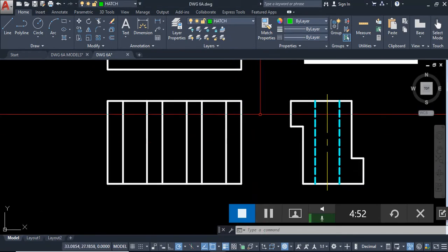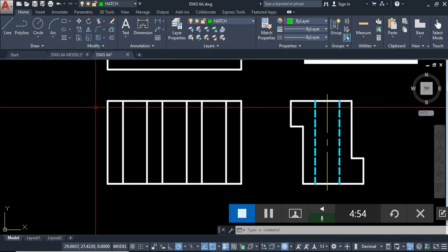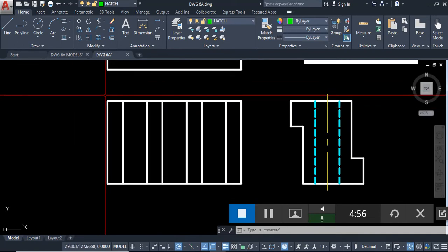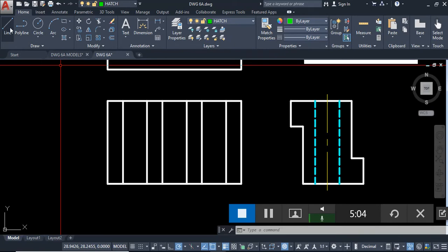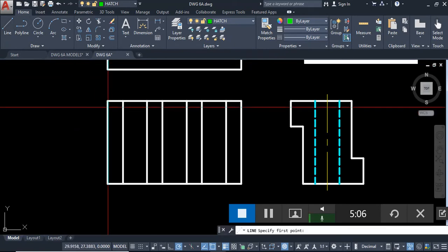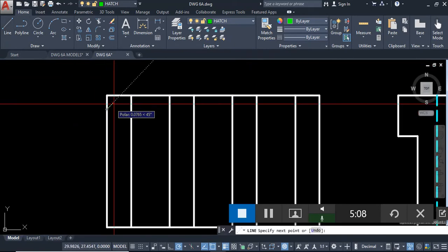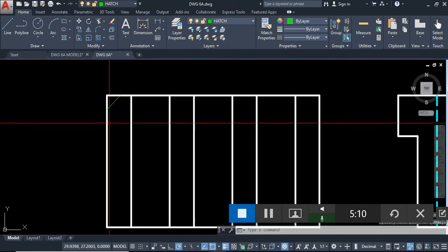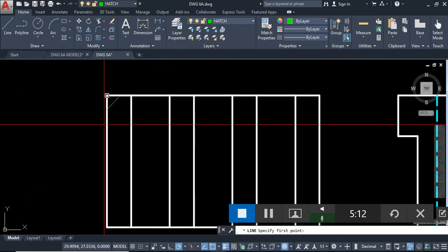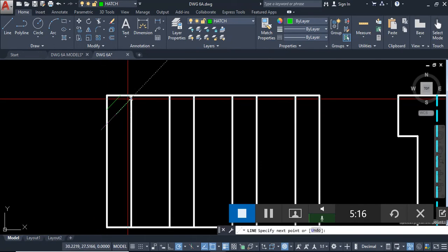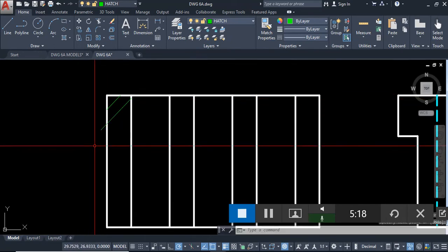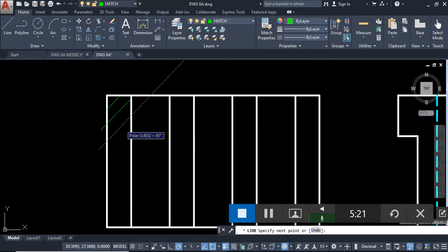All right, by far the hardest thing to do in creating section view drawings is to do the section lining. So there's several ways to do it. One way, of course, is just start over here and at 45 degrees draw a line. And then use your eye to space and draw your next line. And then use your eye to space and you draw your next line.